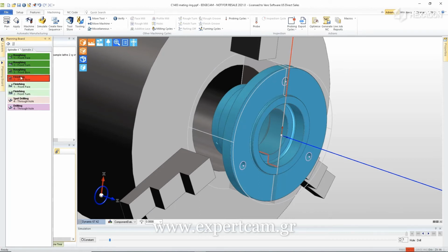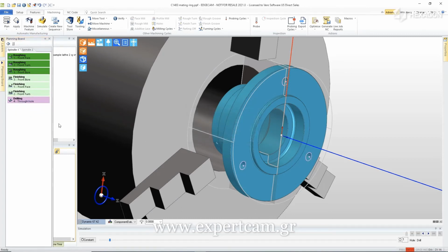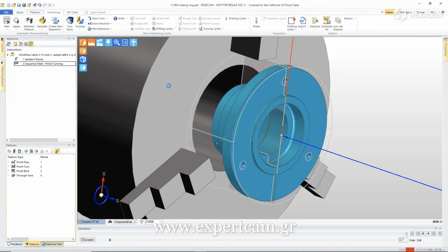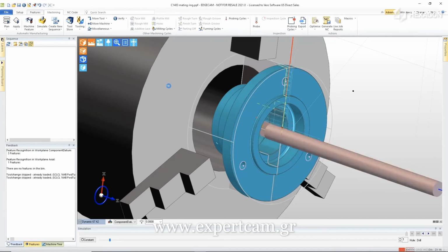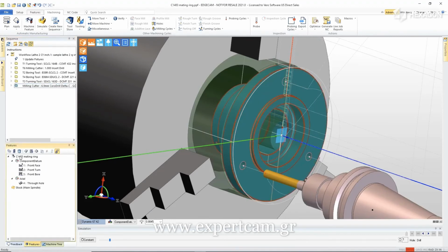So let's adjust the process plan to finish the bore immediately after roughing. Since we're using self-centering drills, there's no need for a spot drill. And using this as our process plan, toolpath is automatically created using a feature-based machining approach. Now that toolpath is built, let's show what happens if there was a late design change.